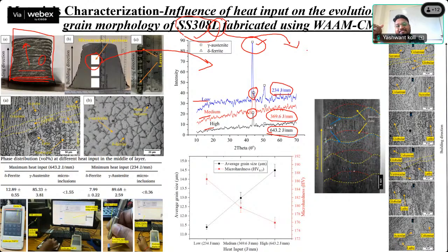As we are melting the austenitic stainless steel, depositing and then solidifying it, some traces of delta ferrite are formed at the high temperatures, like 1100 to 1300 or 1400 degrees Celsius, and then it is retained at room temperature. So it is not completely austenitic. Some traces of delta ferrite are retained in that matrix. That you can see in the microstructure, and we have justified that also. So you can see the microstructural images of these deposited samples.